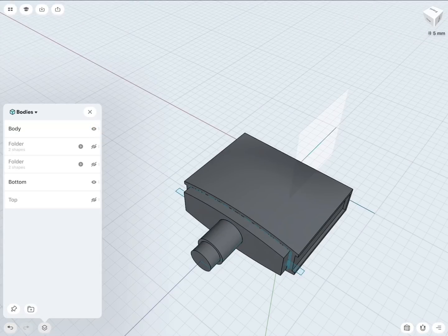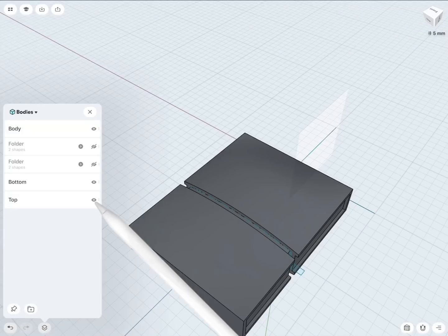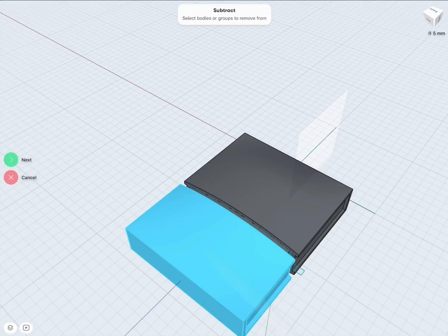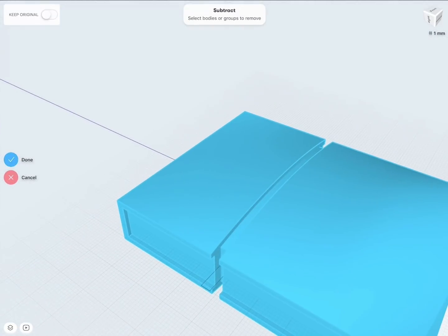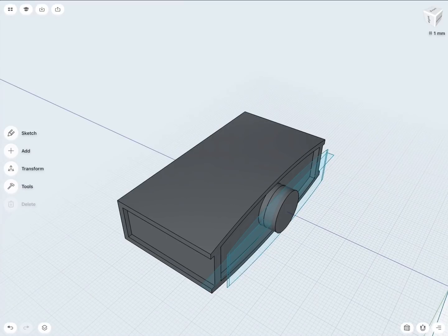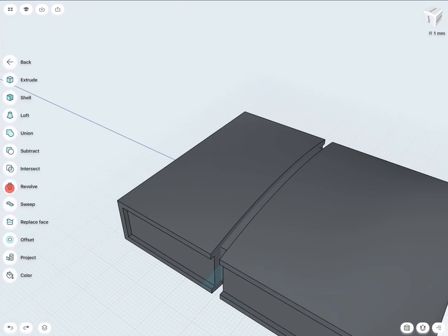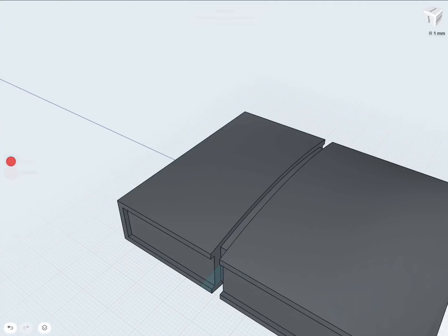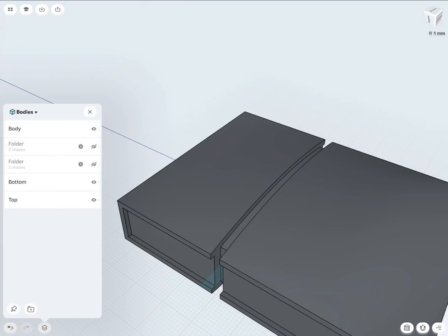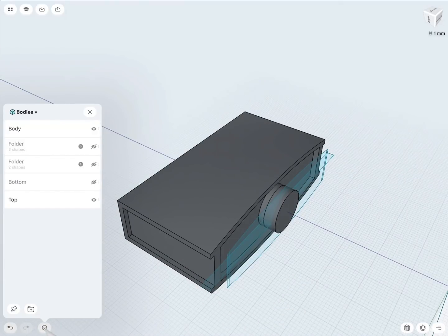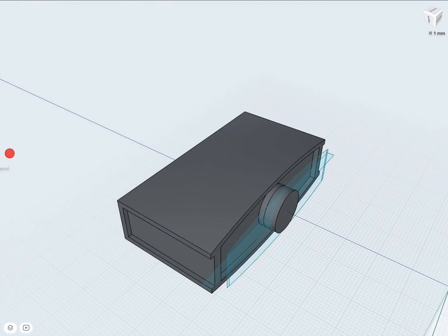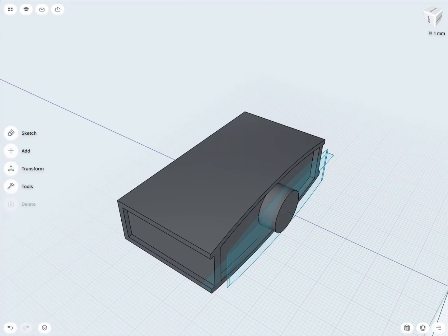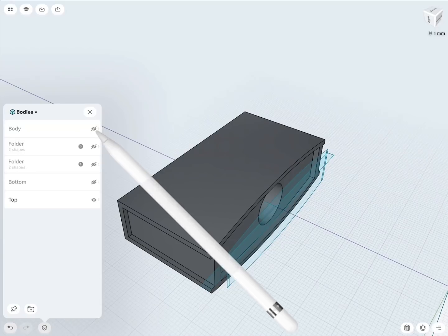There, see that? Now we can turn on the top. We'll do the same. So subtract this one minus this one. Okay, and oh, I forgot actually to turn on the tool, but keep the tool, please. So if we make a mistake, we simply undo. And one more time. Tools, subtract this one minus this one, keep the tool. Very good. So let's see. There we are.